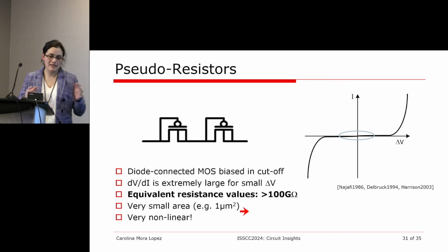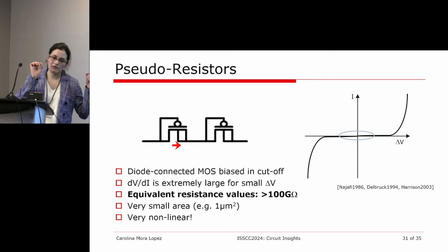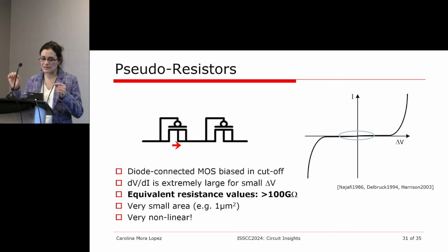But of course, things are not as great as that. You have a lot of non-idealities of this component that you will have to know if they are acceptable for your application. For example, it's a non-linear component, meaning that the resistance of this element will depend on the voltage across the terminals. So it's not the same for a small voltage as for a large voltage.